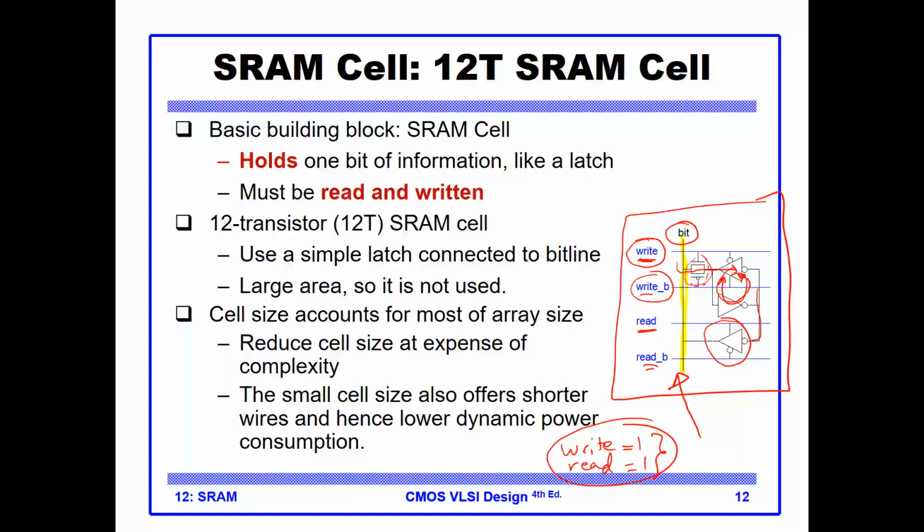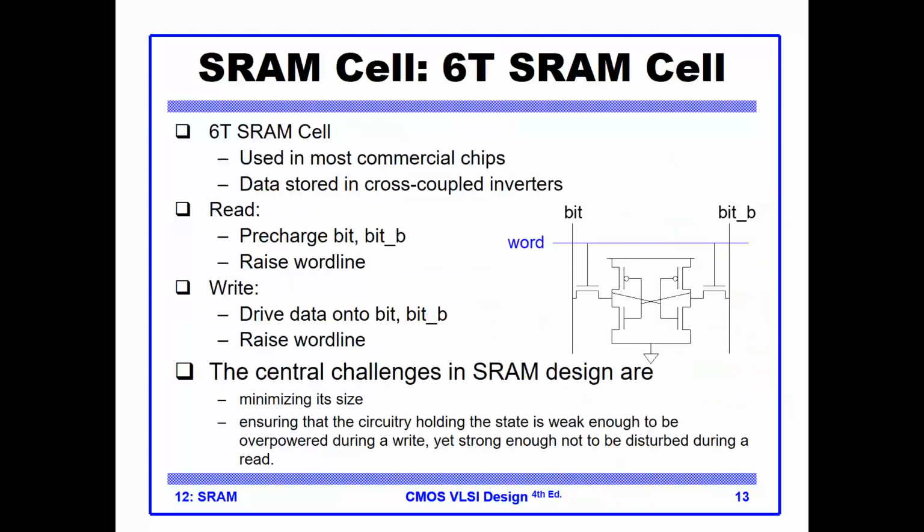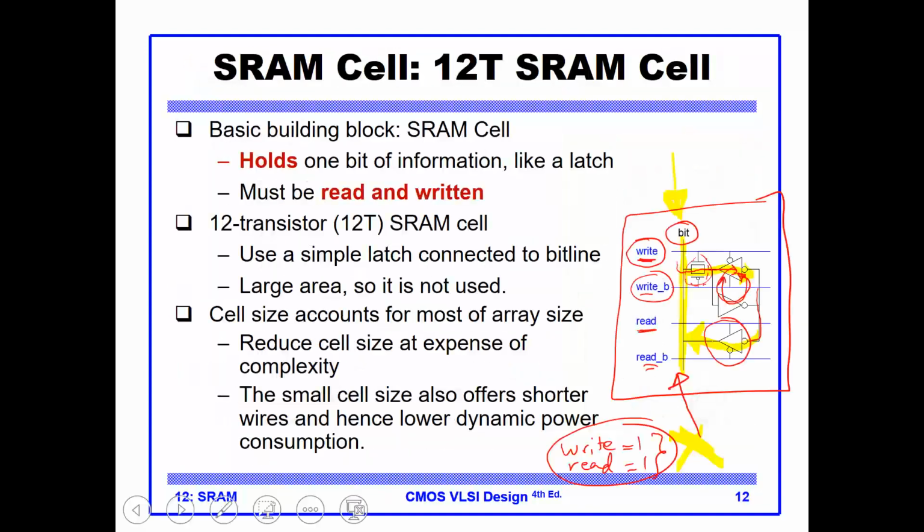So if you are writing to it and reading from it, there will be a clash, because if you are writing here, you are driving the data, because the data that is being written is driven from other circuitry, and at the same time you're trying to read the data onto the same physical wire, then you will have a collision. So this condition should never occur, okay? Because it will cause a collision.